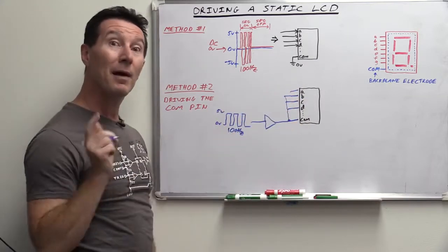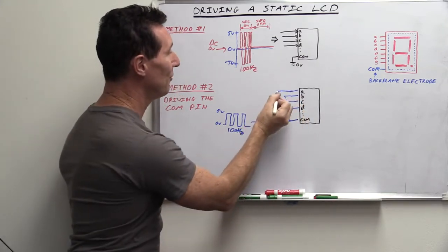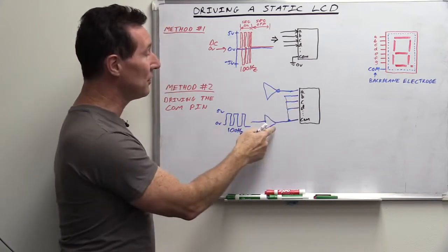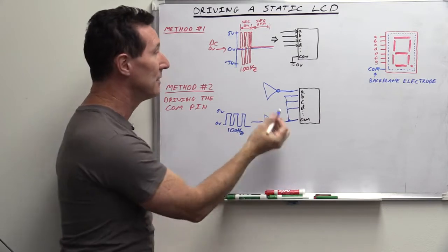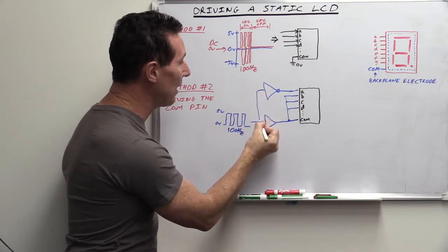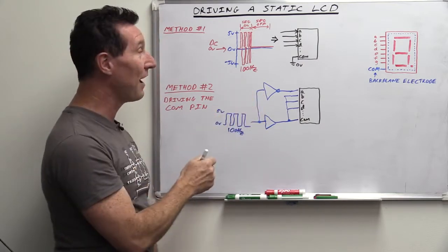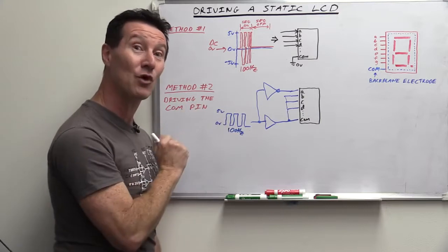No worries. But let's say you wanted to drive segment A here. How do you do it? Wow, it's easy. You use an inverter. You'll notice that we don't have an inverter down here. It's just a driving gate. But if we hook an inverter up there and the same 100 Hertz signal here, but we invert the phase, let's take a look at the resultant waveform.